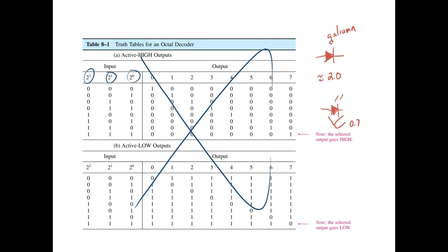If they put that junction so it's clear in a lens, then you can see these lights. But it only works when they're forward biased. So that means to turn this thing on, I've got to make the cathode at least 2 volts more negative than the anode, or make the anode more positive.